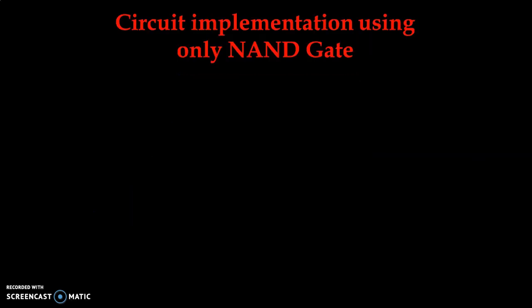Now let us take one example in which we have been given one switching function, and based on the given switching function, we will be implementing the logic circuit, but now with only NAND gates. The function given is A bar dot B bar plus A bar dot C bar plus ABC.